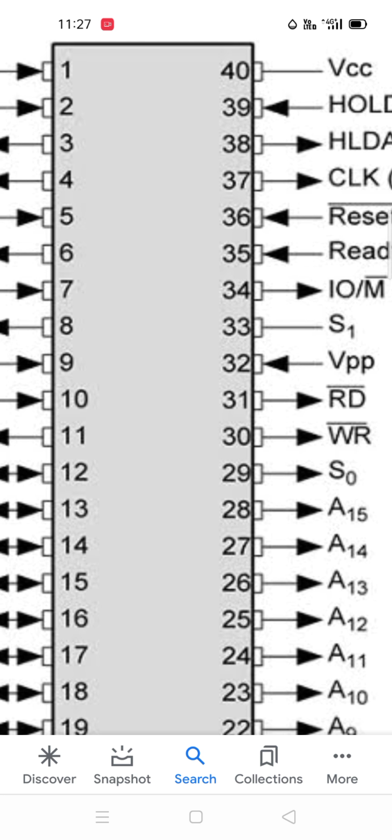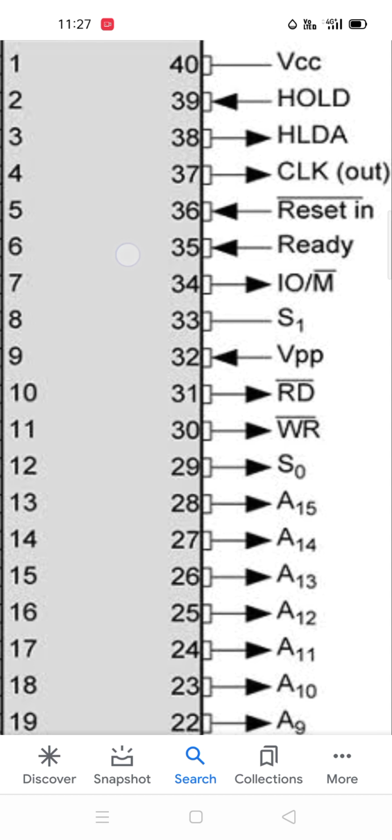Okay, that DMA is what gives the hold signal, HOLD. So when the hold signal comes, the peripheral is doing some kind of work, a direct transfer of memory or IO from one device to another device, or one device to a memory device, or memory to memory. Those kinds of things are HOLD and HLDA, hold acknowledge.